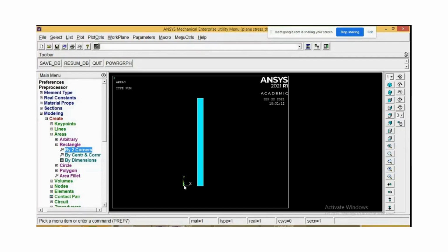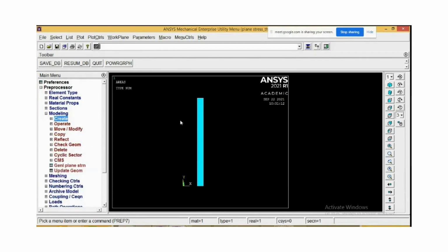Because the pressure vessel is subject to internal pressure, it is an axisymmetric problem. About the y-axis it is symmetric, right? So we are only taking one cross section area, and we will apply the pressure and evaluate the result for the overall pressure vessel using axisymmetry.